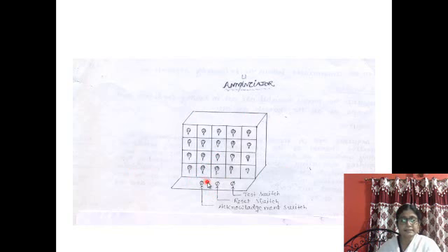Then the error is acknowledged by the plant. After pressing the acknowledgement switch, the hooter will turn off and the corresponding lamp will remain glowing.